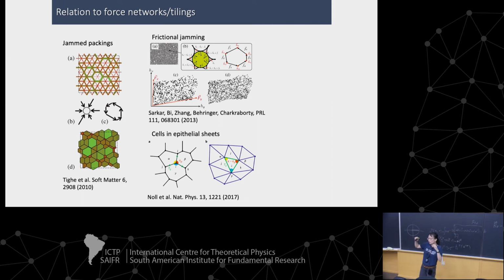So when you only know the boundary stress, you don't necessarily know what's happening in the middle. If we know perfectly what the force-displacement relations of every element are, you know. But in a real experimental system, you sometimes don't know. So that's basically the so-called Edwards ensemble. You know the boundary stress, but the internal stress distribution you don't know. And here the authors proposed that, for example, you start from a triangular lattice, you have many states of self-stress.